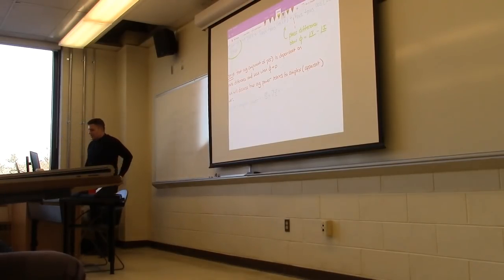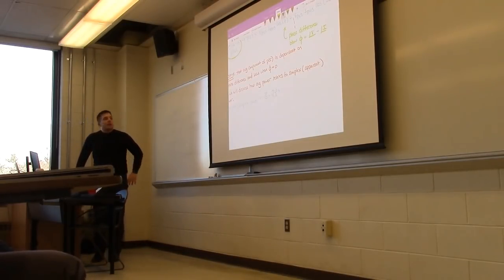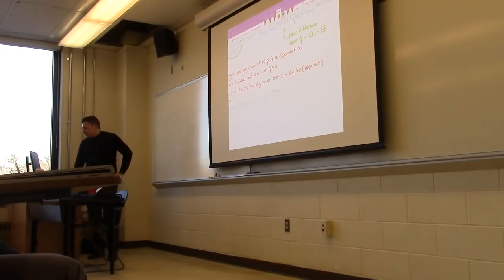So we're taking the conjugate of the, well, actually it's the same thing as taking the conjugate of the whole thing. And does anybody remember what taking the conjugate does? Flips the imaginary form. Yeah, that's all you've got to do. If it's in rectangular form, flip the positive to a negative. If it's in polar form, you flip the sign of the angle.